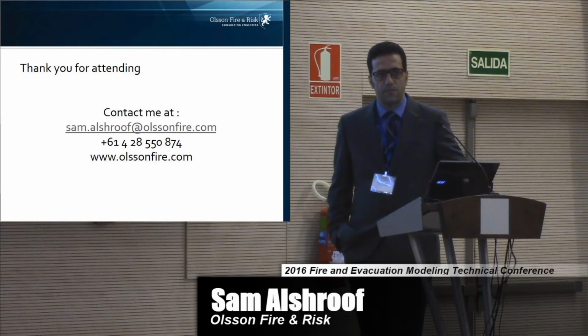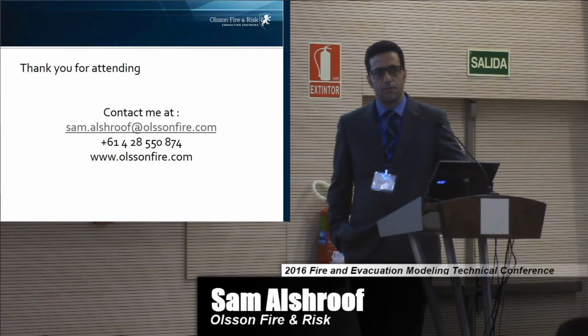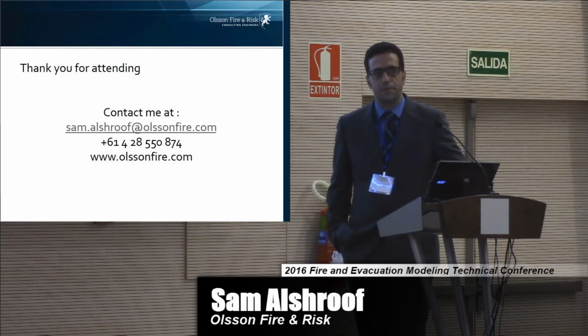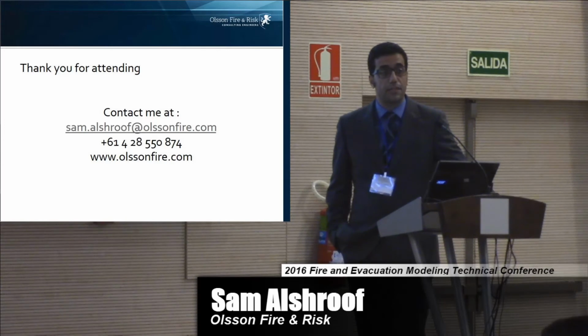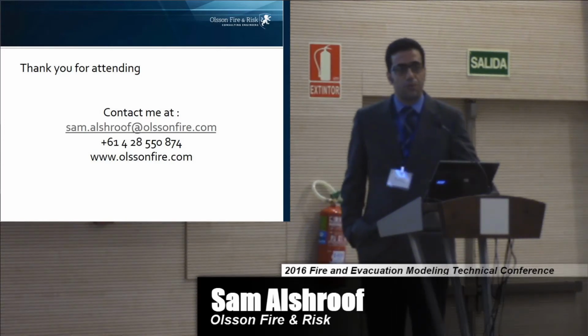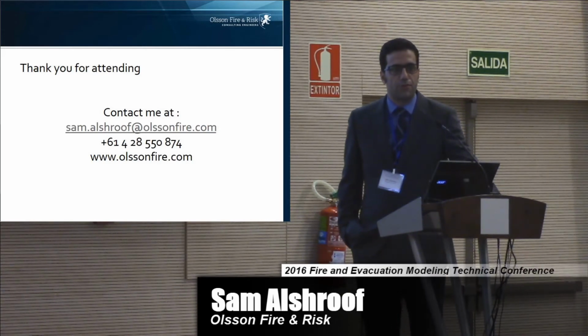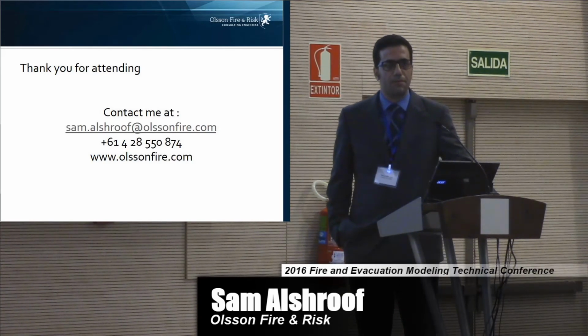It was much better, and also if you use the HVAC feature for modeling the JETFAN, you can reproduce velocity at the JETFAN much better than with other solutions. I think the turbulence model they use now is much better than the static and dynamic one we used to use before. So yeah, definitely there's improvement. I think it can be improved more with the code development as well. I'm pretty sure that at one stage it will not be that big a problem.